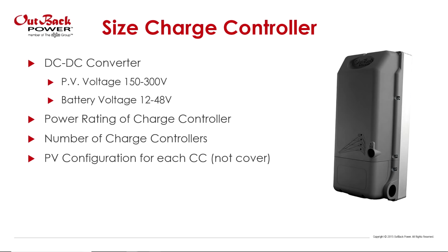When you size a charge controller, you have to be aware of its power rating. You have to make sure that the charge controller can pass that power from your array to your batteries. It's not going to limit that. And then you have to consider the number of charge controllers you might need and the PV configuration for each charge controller, which we will not cover.